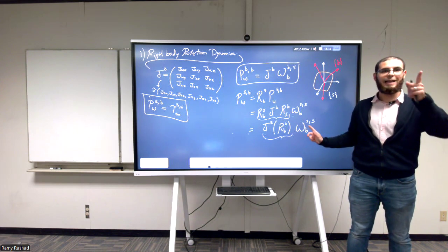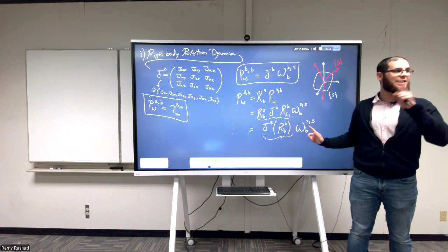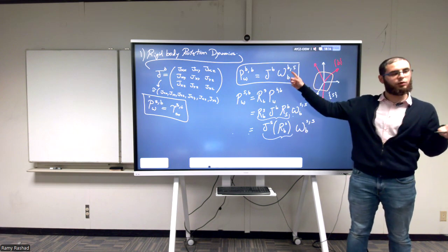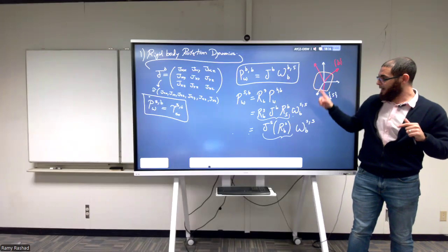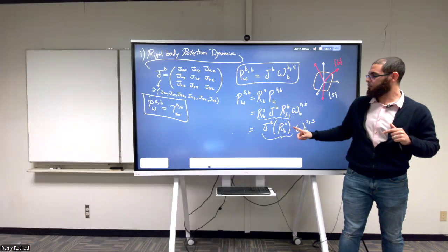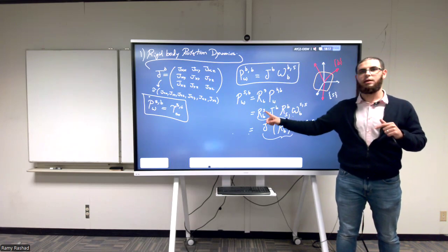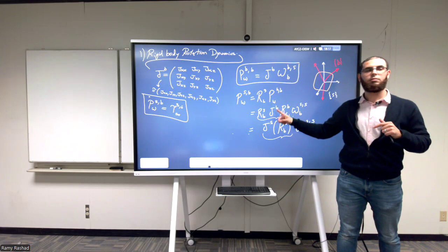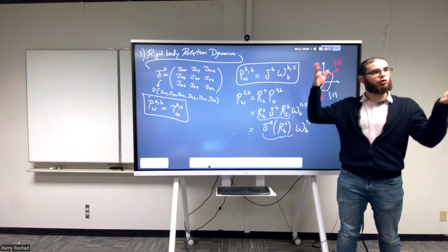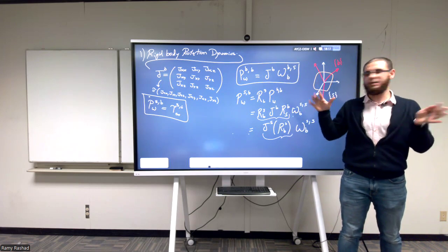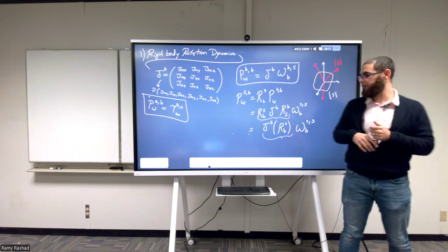What is the transformation that we use to relate the twist? The adjoint matrix. So the adjoint is a 6x6 matrix that will relate us from the twist in frame S to the twist in frame B. Then what you see inside of here will not be R, J, R, it will be adjoint, the generalized inertia matrix, which will be 6x6, multiplied by the adjoint, one which is the inverse and one is the transpose and one is not the transpose. We're going to see.